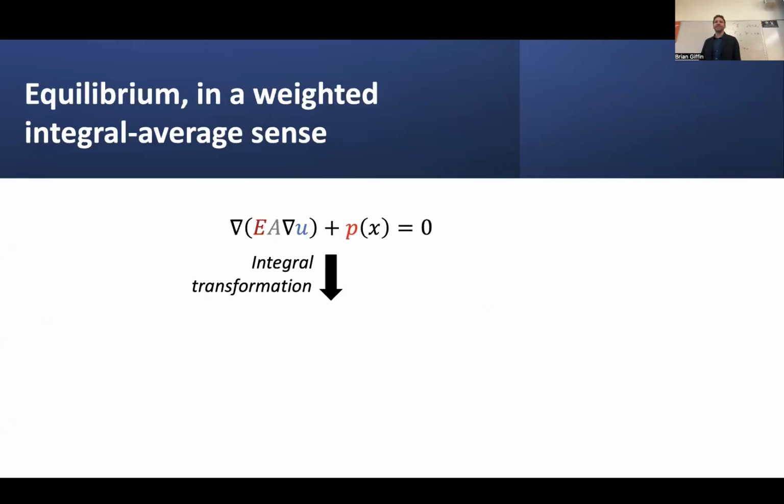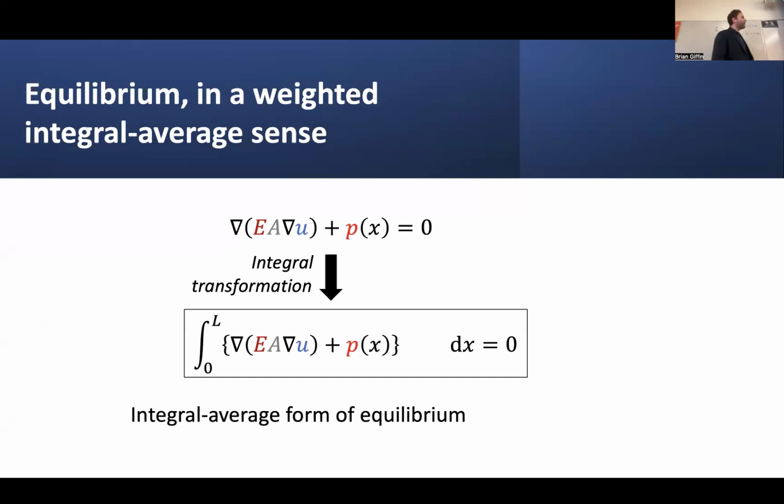All right, so to do this, we start with our governing differential equation expressing equilibrium in this pointwise sense. And we're actually going to go backwards from the way that we originally derived these equations. We started in deriving these equations by posing equilibrium not in this pointwise sense, but by describing equilibrium in an integral sense. We were integrating this whole interior integrand term over the domain of some structure of interest. And that's how we originally posed statements of equilibrium on, let's say, some one-dimensional bar.